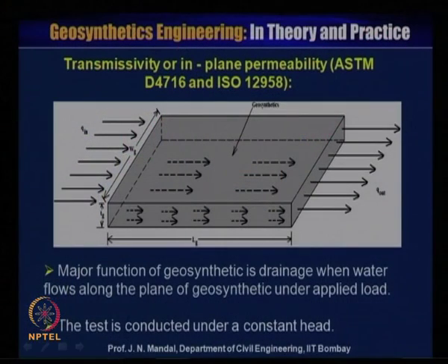Similarly, there is another very important term, that is transmittivity or in plane permeability. This is as per ASTM D4716 and ISO 12958. Here you can see that this is the geosynthetic material, and major function of geosynthetic is the drainage.